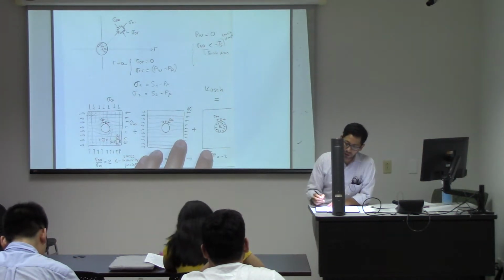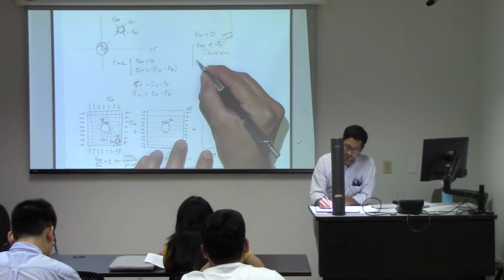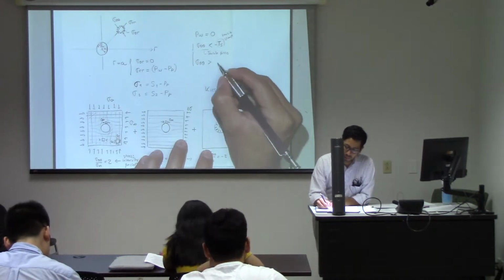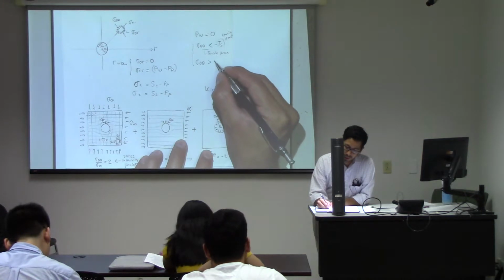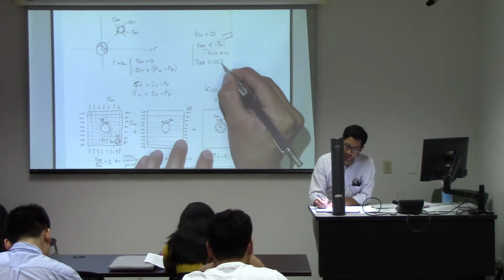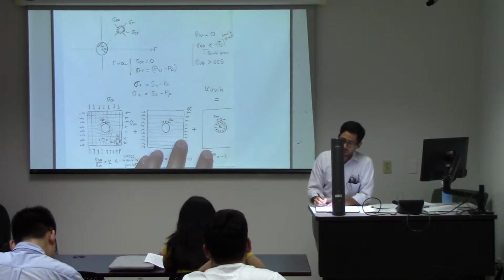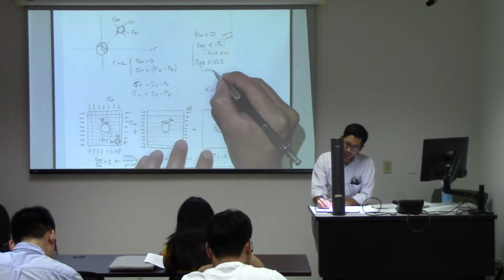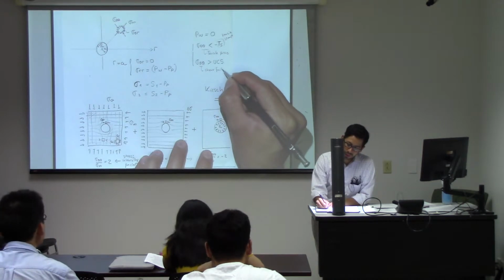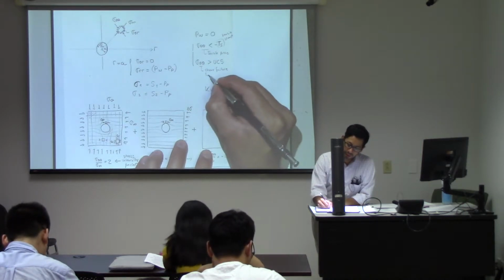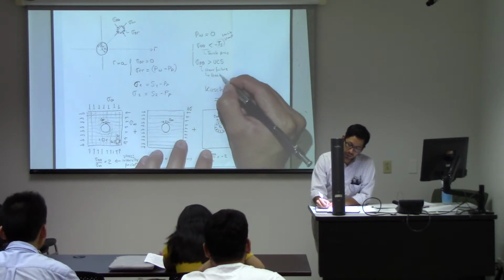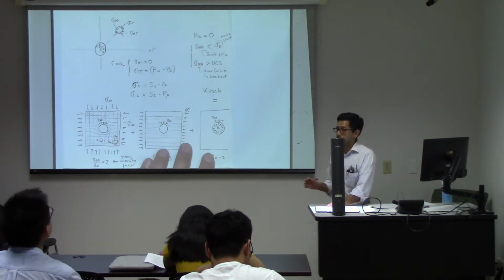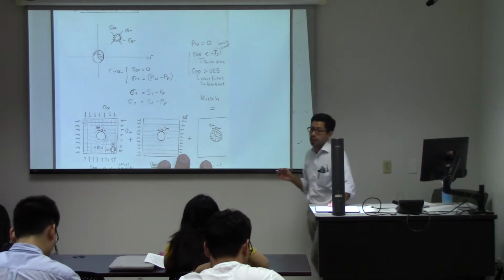And on the other hand, if your sigma theta theta goes above the unconfined compression strength value, you're going to have here a shear failure, and you're going to have something which is called a breakout. We'll go, I repeat, we'll go in detail about that later on.